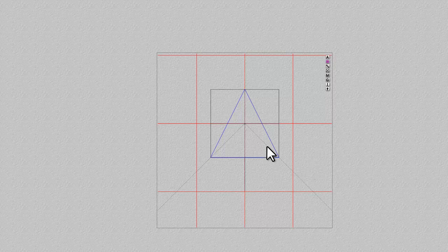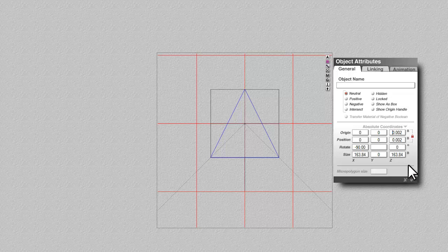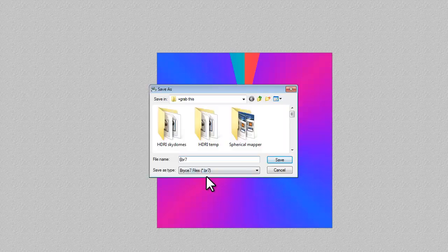We'll go back to T1, I need to capture the other side. So if I select all the planes together, and then go to the attributes and move both of them slightly north, so just get rid of that minus sign, switch to the render, and render that. Okay, so again the artifact, but we can get rid of that. So I'll file, save as, and call this B1.